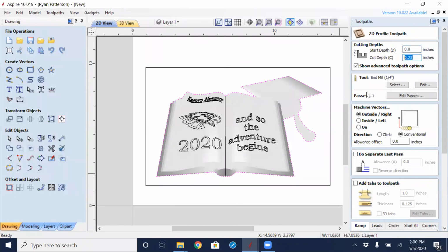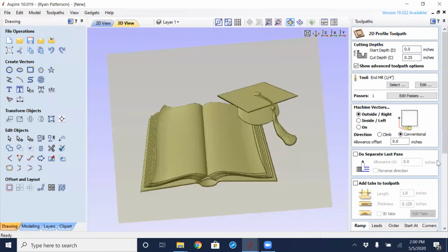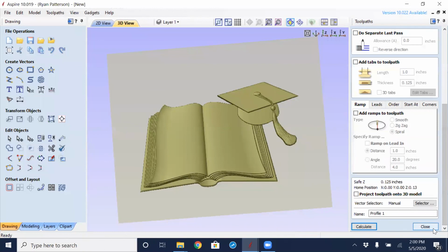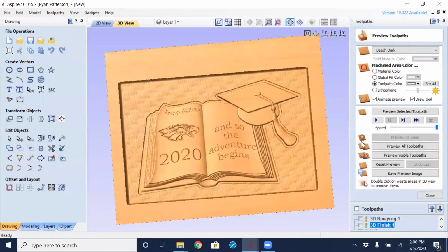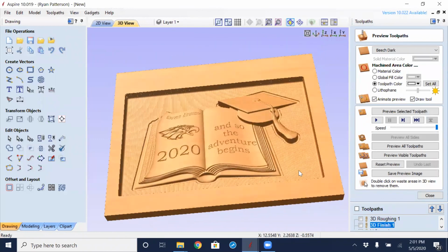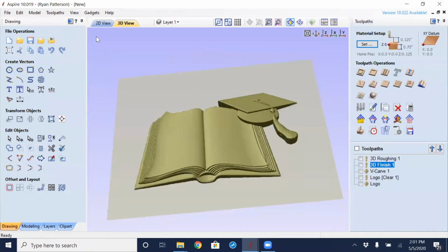And the total cut depth. Now, we could play around with this a little bit. I'll just point this out. This is where a start depth could come in. We could see that we're down at -5.5. So we've already removed like a quarter of material in that roughing. So we could actually start down, well, actually a 1/2 inch. So our start depth could be that 5.5. So let's just view what that is.